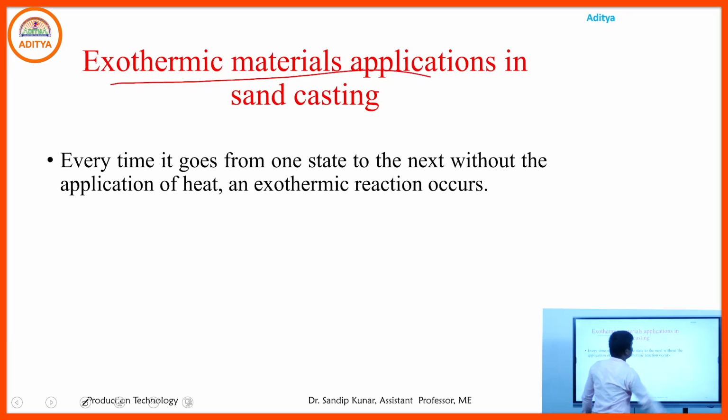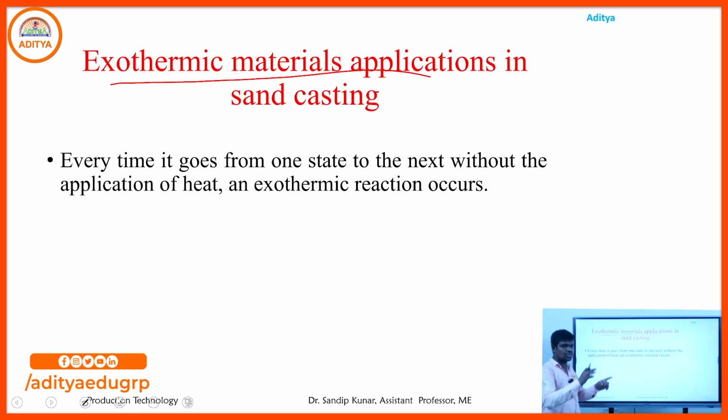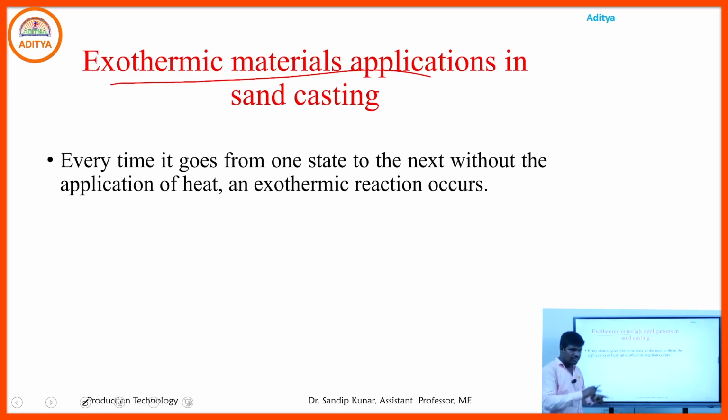Some exothermic materials are used in sand casting. Why do we use exothermic materials? Sometimes we use them for maintaining the fluidity of the molten material. If we are storing extra material in the riser, it may freeze. So we use exothermic materials to maintain the fluidity of the molten metal.